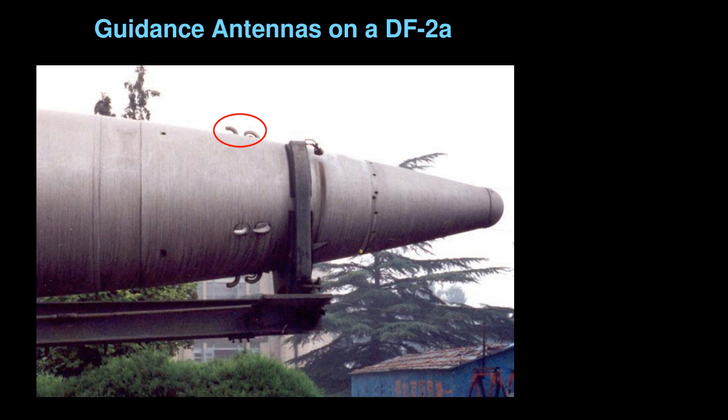And when it tears off, that can result in forces that disrupt the trajectory, both because the process of that happening can cause the warhead to spin, but also if it breaks off and doesn't do so cleanly, now you've got edges and rough metallic flanges that can cause problems with the atmosphere and atmospheric forces as you go in. And that's in fact what happened with the stretch Scuds, the Al-Husseins that were fired by Iraq against Israel in the 1990 Gulf War. When these tanks broke off, it caused spiraling of the warhead, which made them essentially impossible for the Patriots to hit. So it was both an inadvertent countermeasure, but it also made them very inaccurate.